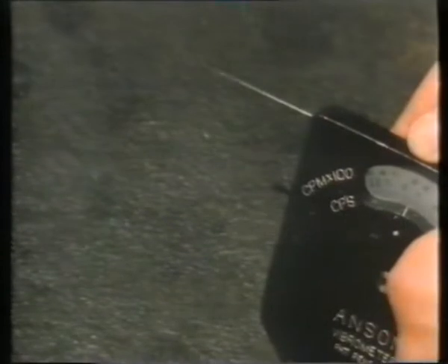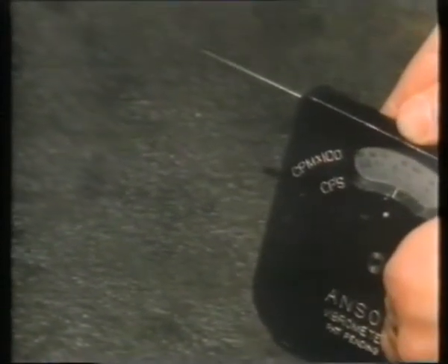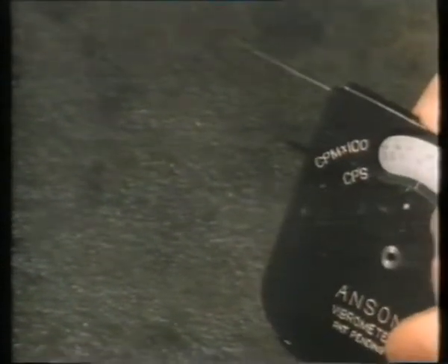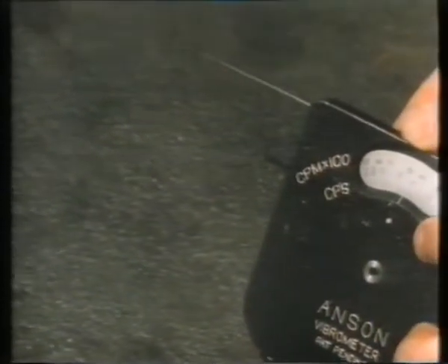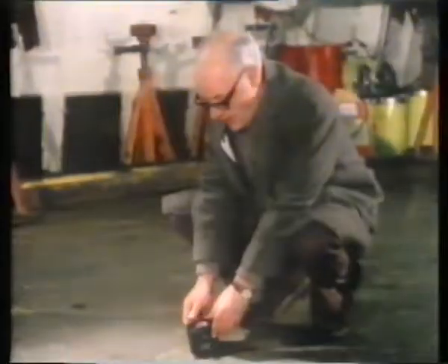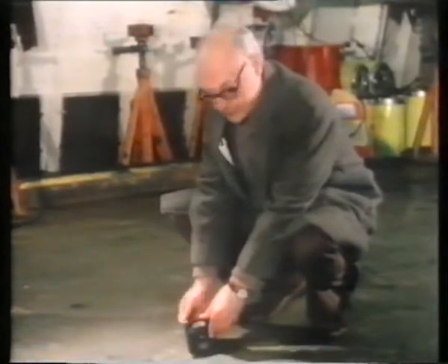Now, every length of projection resonates at a different frequency, and there is a scale on this instrument which is calibrated in terms of the frequency of resonance of each length of projection. At the moment, for instance, nothing much is happening, but if we make the length a bit bigger, sooner or later we'll get resonance. There's resonance here now, at a frequency which the scale says is about 13 hertz, or 13 cycles per second.